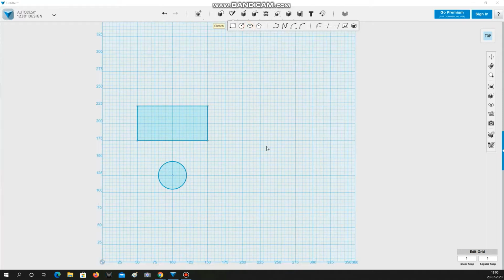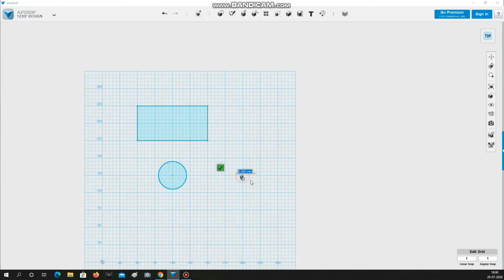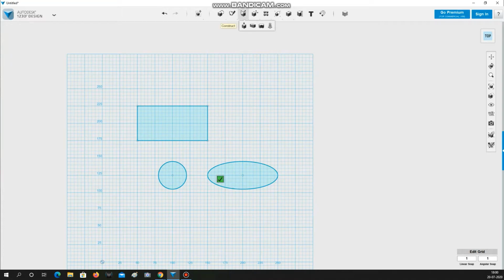Then you can go to the ellipse. The ellipse should be the center, then specify the first axis, and then select the point on the axis, the point on the ellipse. Yeah, so that way I would be done with the ellipse.